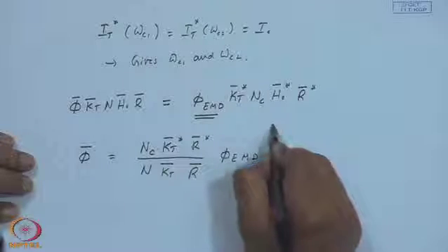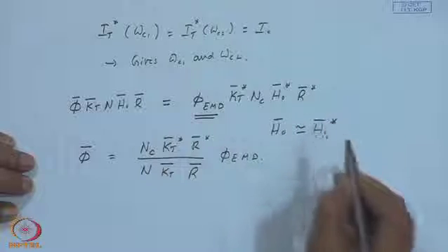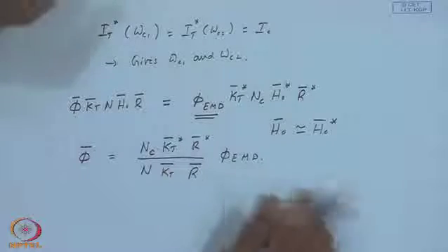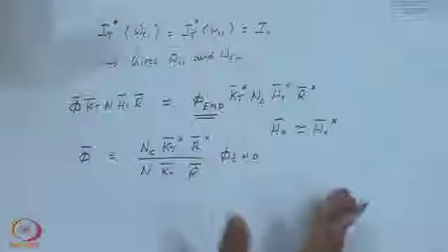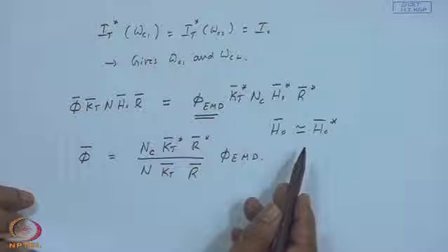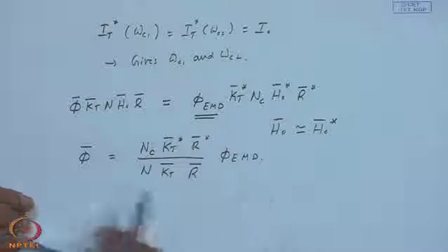Of course, I have approximated H 0 bar approximately equal to H 0 bar star, because it is not necessary that these higher clearness index values are only towards the end or towards the beginning of the month, they are randomly distributed. Still the effective declination, mean declination will more or less be the same as that of the entire 31 array of the clearness indices. So, we can safely assume H 0 bar equal to H 0 bar star, even otherwise it is not a big issue to calculate these things, because it is an analytically calculable quantity.